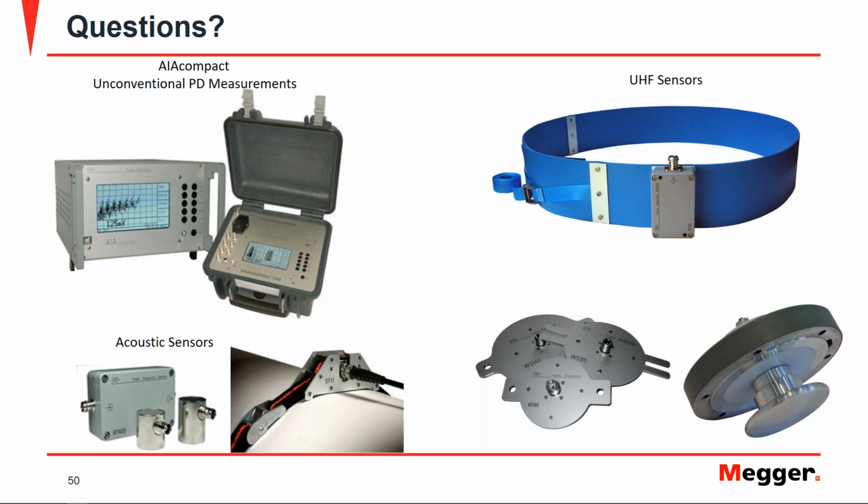So there you could still use these same sensors. The sensors are still going to be pretty much the same as far as external flange sensors. You could use maybe CTs as well, and you could utilize these for permanent installation and monitoring of your GIS system.